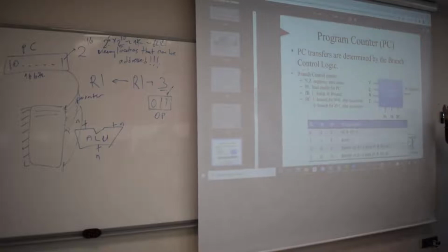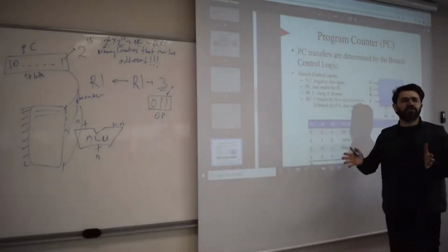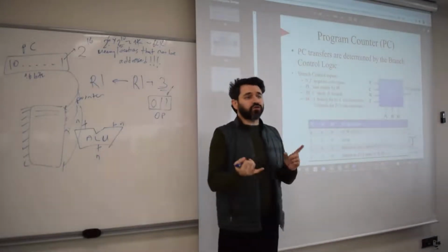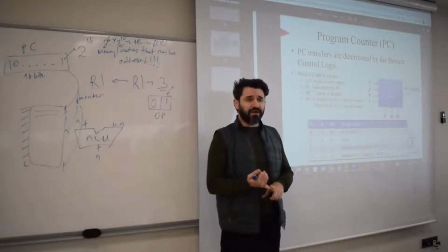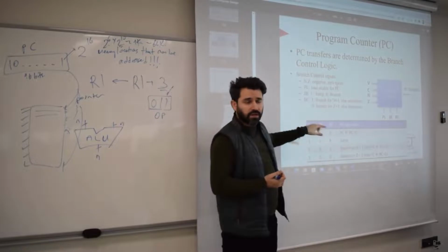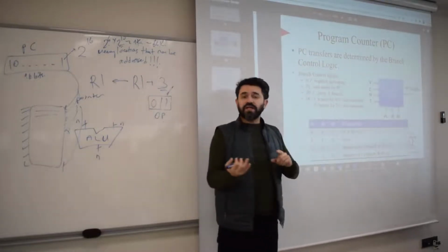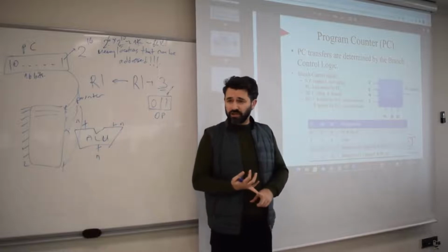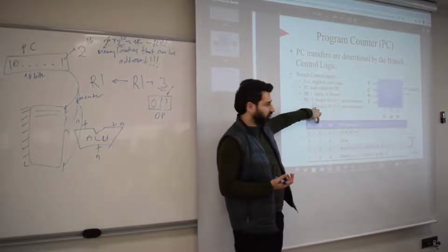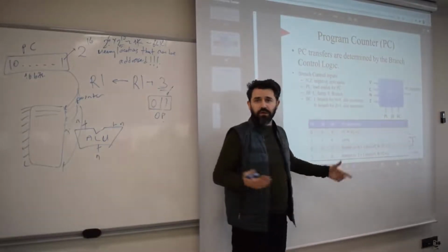We talked about the control bits that are required to select between those control instructions. First question is, do we have a control instruction or not? That is determined by PL. If we have it, then PL becomes 1. Then the next question, is it a jump operation or a branch operation? That is determined by JB, jump or branch. If it is 1, then it's a jump. If it is 0, it's a branch.